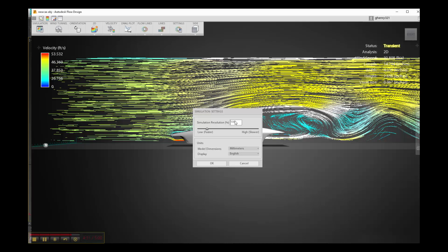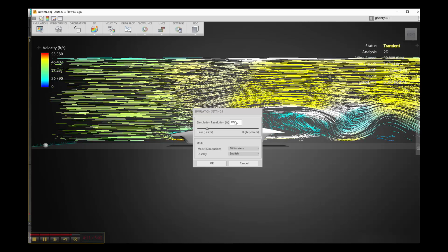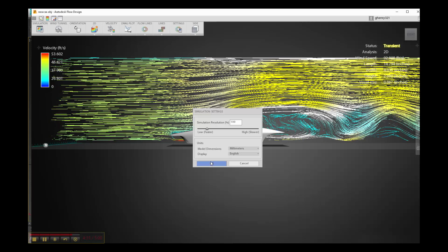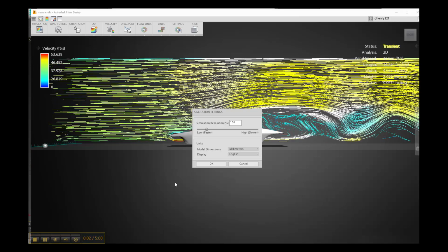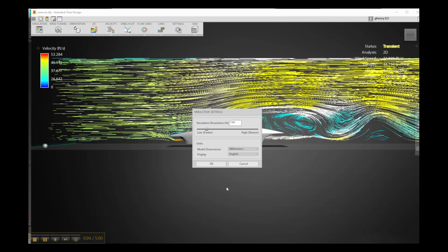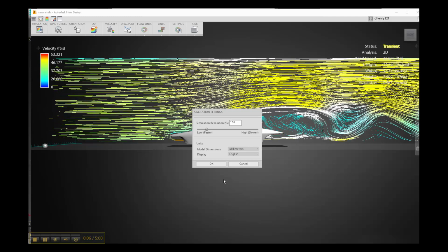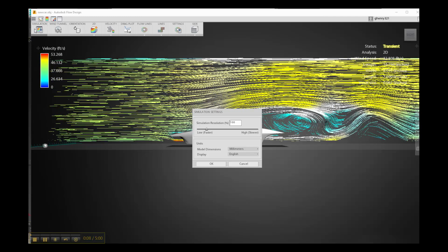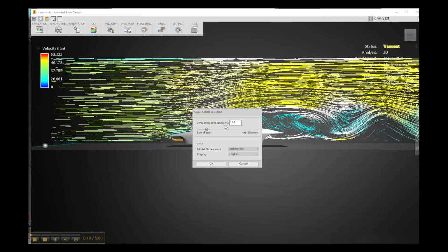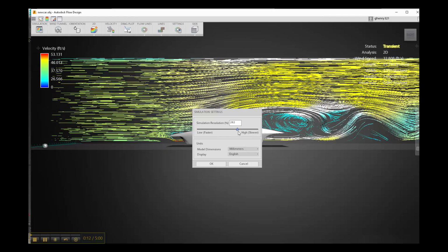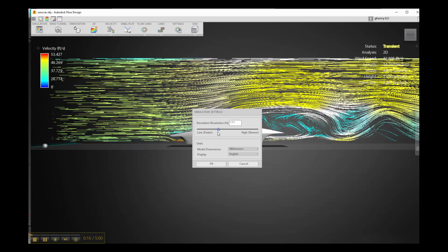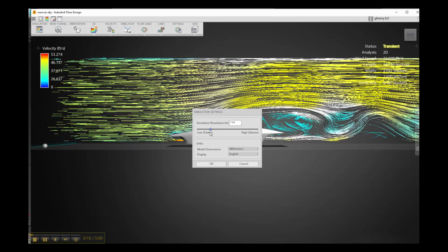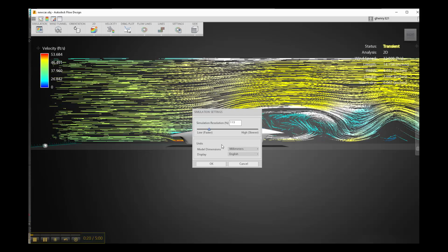And in the next video, I'll quickly run you through this program. Gang, we're getting near the end of our journey here. So hopefully in 5 minutes I can give you the 101 of Flow Design. So anyway, simulation: I clicked open simulation settings, faster, slower, or higher. You want to keep the simulation resolution to around 100, unless you have a really powerful computer, then you can crank it up.